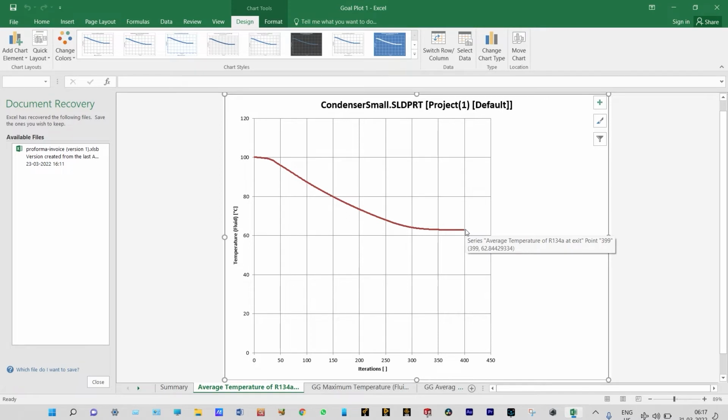We have already said that before. We can reduce the temperature at the exit of the copper tube by putting more fins with lesser thickness, because if we provide more fins, the surface area will be more. In that case, better cooling will be there, right? To reduce simulation time, we have decreased the numbers of fins, and we have provided more gap between the fins. That can be reduced to have better cooling. Okay.